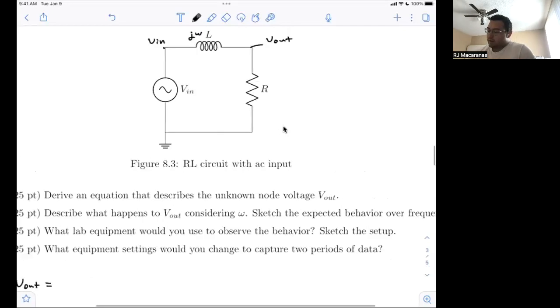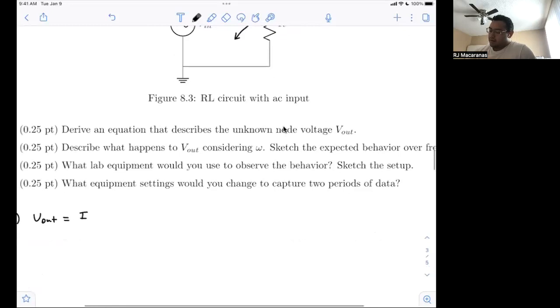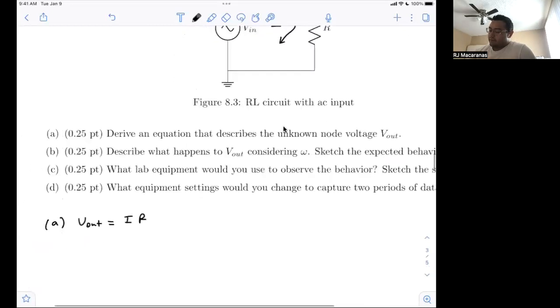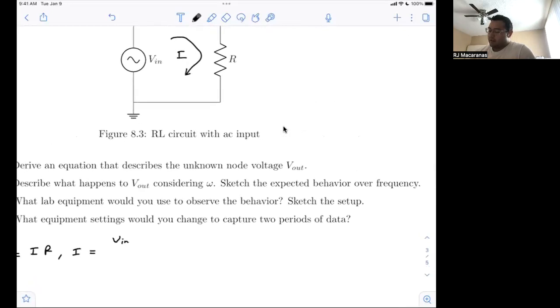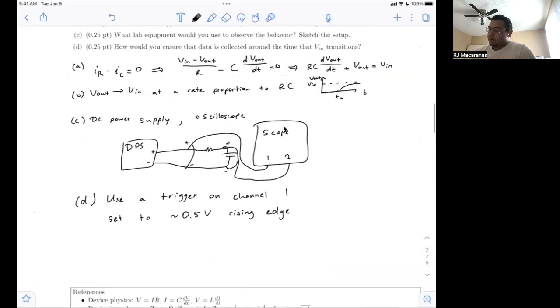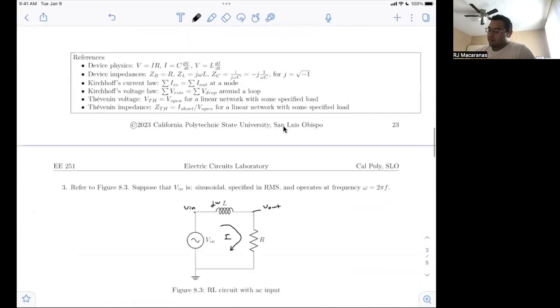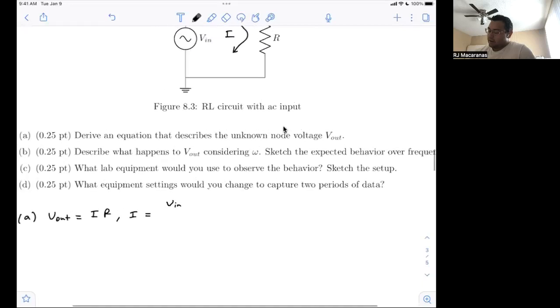well, there's some current here in this loop. Right? So it's actually this current times R. And what is that current? So the current is this input voltage, right? And I'm using this different approach than the other one, but you should just know that you can use any kind of method to solve this. So in this example, I'm just going to use that current times R. So that current is I, or V in, divided by the magnitude of this equivalent impedance, right?